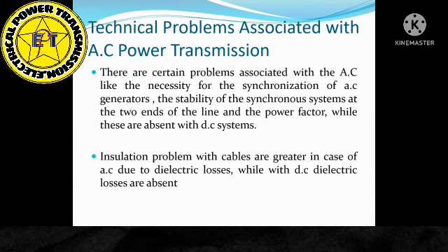If your system is operated at 60 hertz, then all your power stations must be operated at 60 hertz. This is an issue, but not in a DC transmission line. Frequency is of no concern. You can mix all the power of different generated frequencies in a centralized power pool.